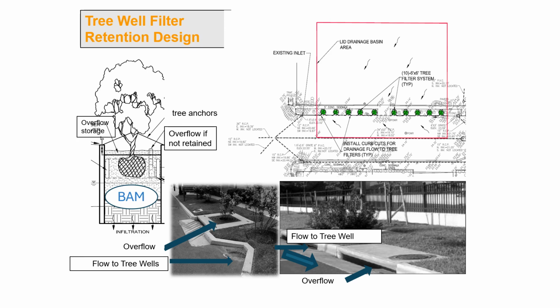To evaluate the effectiveness of these designs, specialized software like BMPFast is often employed. This software can assess the annual removal of a quantity of water, quantify pollutant removal, and even estimate groundwater recharge and the average concentrations of pollutants in the treated water. Ultimately, every one of these systems, regardless of its specific design, has a defined treatment volume and an associated depth of treatment that corresponds to its catchment area.